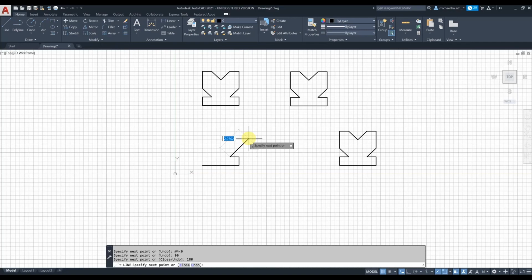So we're gonna do 1, 1. Alright, so we use dynamic input with Cartesian coordinate with relative coordinate entry. Next we're going to use polar, so that will be length will be 2. Press tab key to enter the angle. That will be 90 degrees.